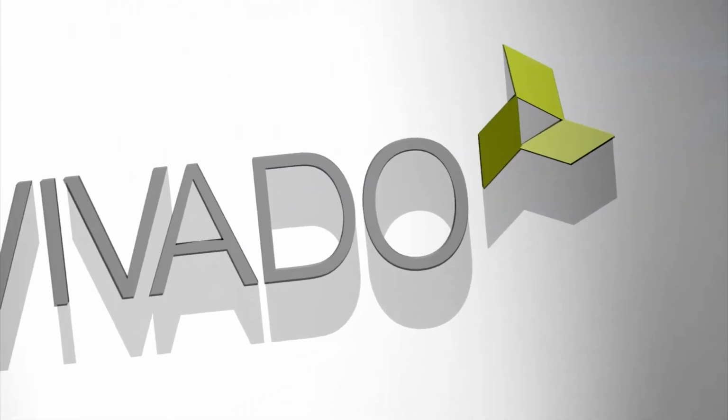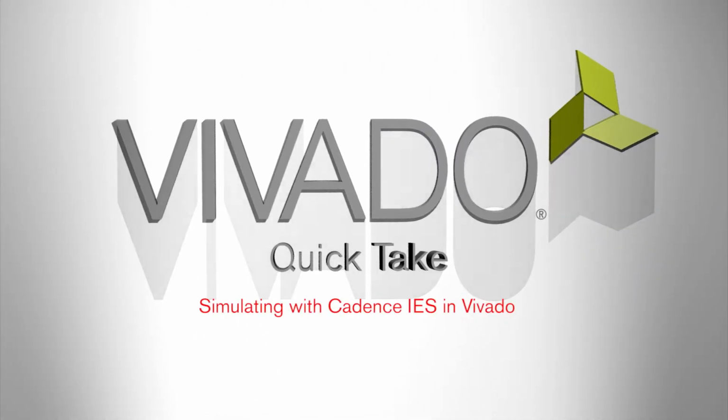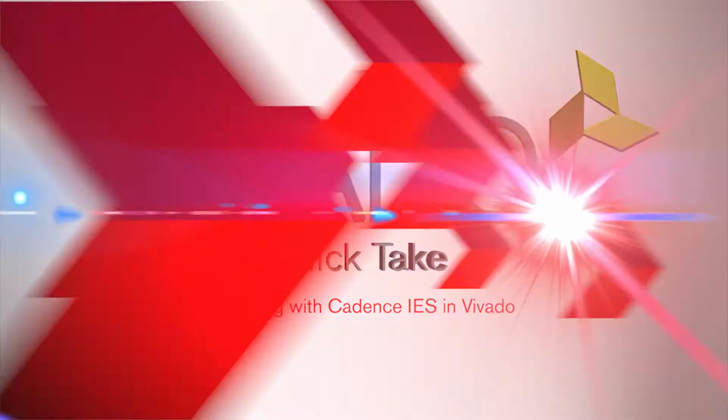Hello, and welcome to this Vivado Quick Take video, where we'll be discussing how to simulate using Cadence Incisive Enterprise Simulator, or IES, from the Vivado Integrated Design Environment. Today, you will learn how to set up the tools and invoke IES from within the Vivado GUI.